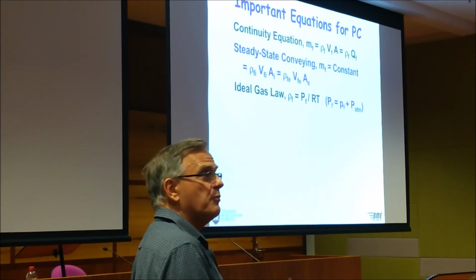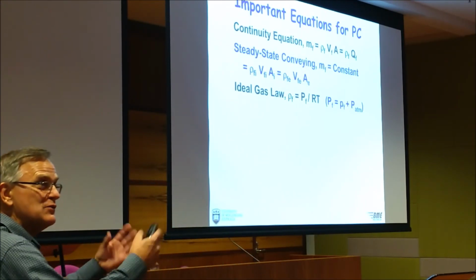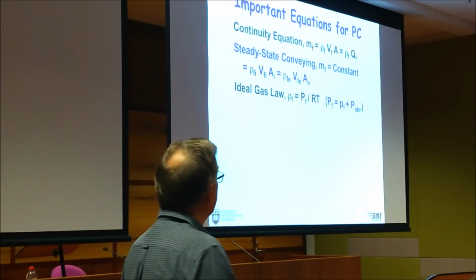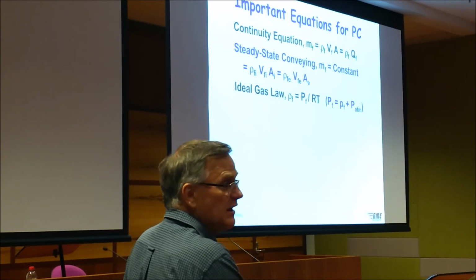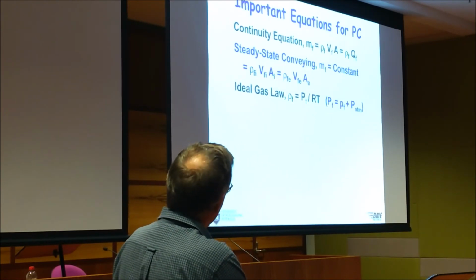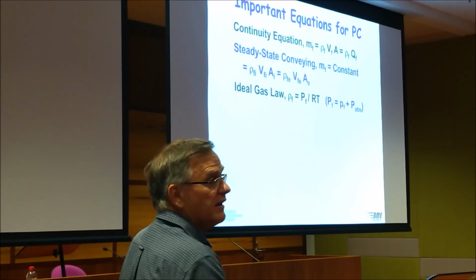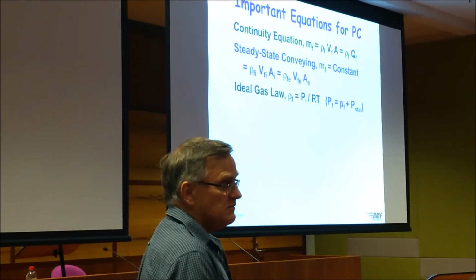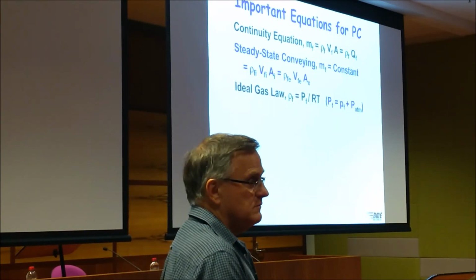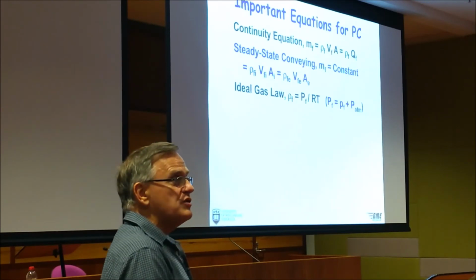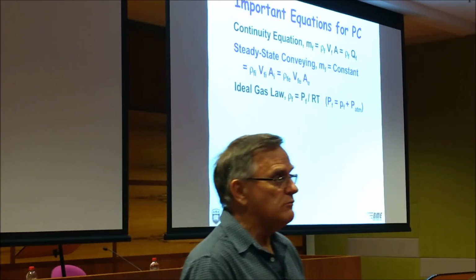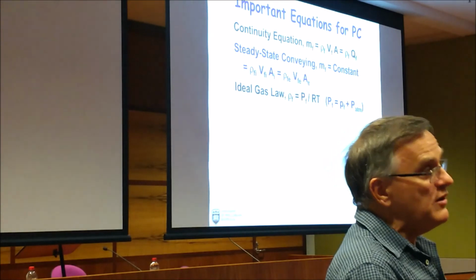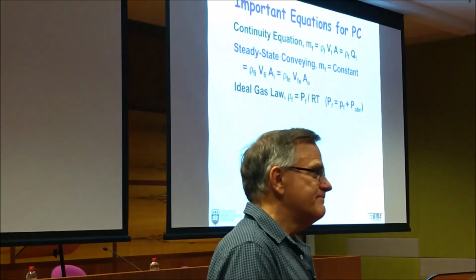We don't have holes in a pneumatic conveying system, otherwise you lose powder. So assuming that you don't have any holes, rho V A at the inlet equals rho V A at the exit. Yes? Does the temperature change from the initial state to the final state? That's a very good question. Well, the answer is no. Pneumatic conveying, for most cases, is isothermal.